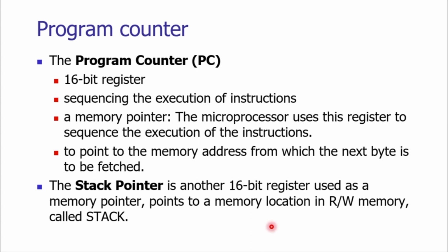The stack pointer points to a memory location in the read or write memory. It is called the stack. The beginning of a stack is defined by loading a 16-bit address in the stack pointer register.